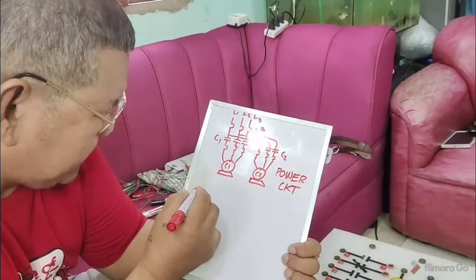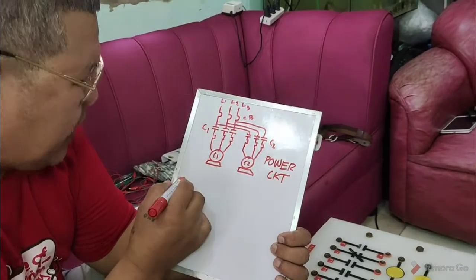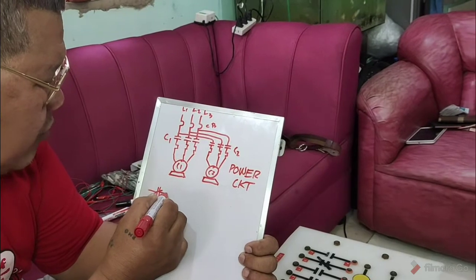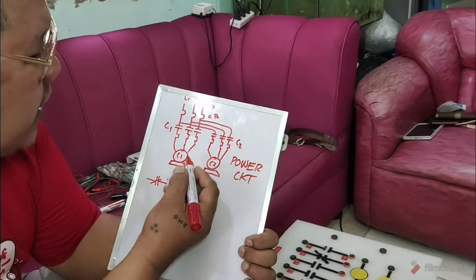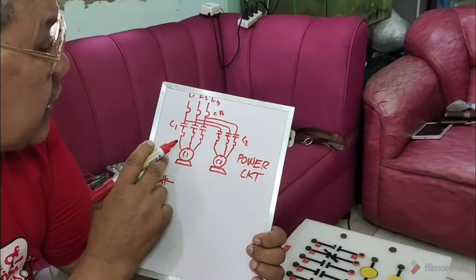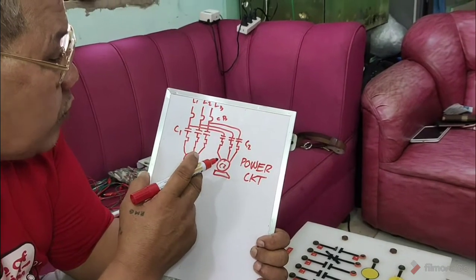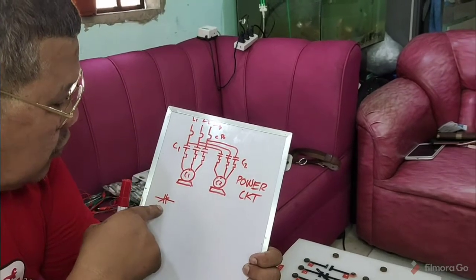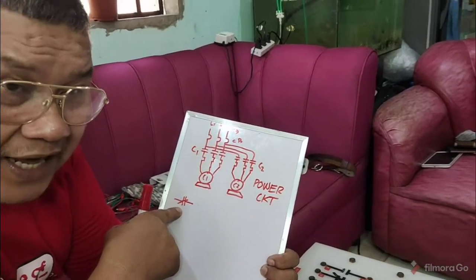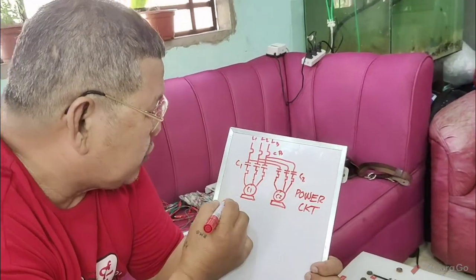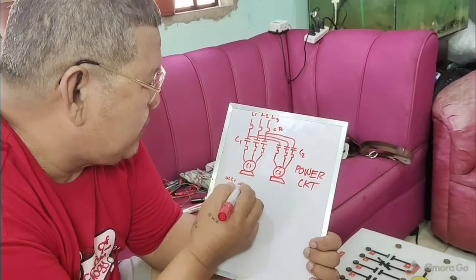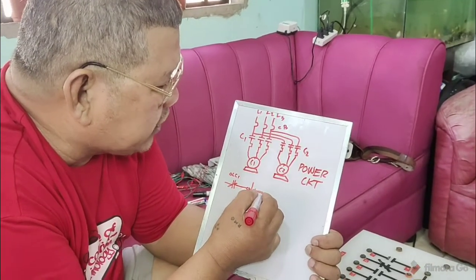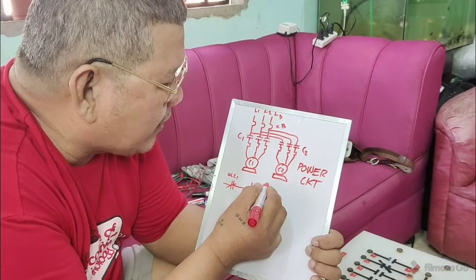So of course, there is also another one here, no? You have your overload contact. Don't ever forget the overload contact. Considering that you have two contactors, you should also have two overload relay contacts, right? So this is OLC1. Then this is your on button, intended for conveyor number 1.